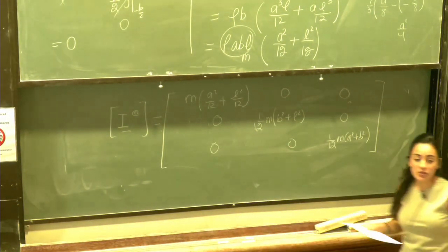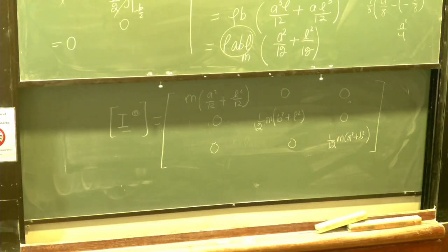So this is the connection between the inertia tensor that we derived and the matrix and the components in these tables. So notice that for all of these shapes, they take the basis, the gravitational basis, to be along the eigenbasis. So for all of these shapes, the products of inertia are zero, but that's not always the case, because what we're going to consider later on is not just one rigid body or one simple shape, but a system or a rigid body that is a composite of these shapes. Any questions so far? Questions?